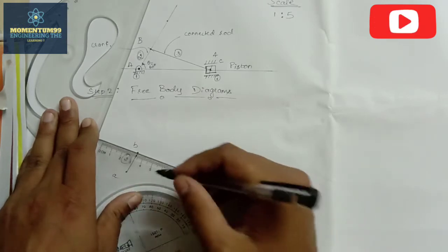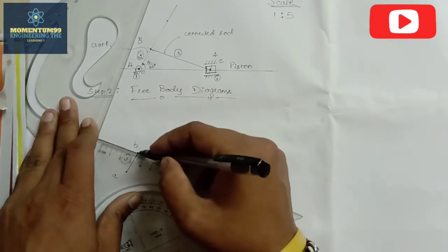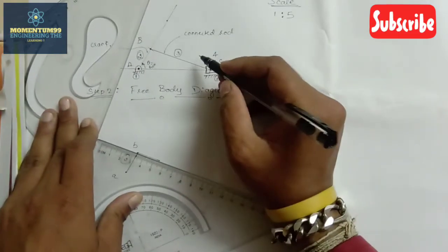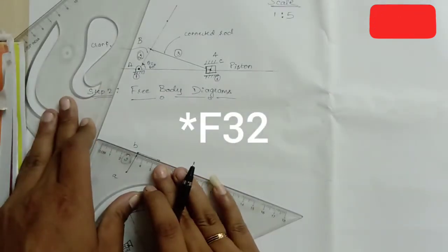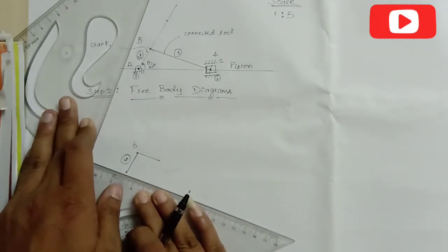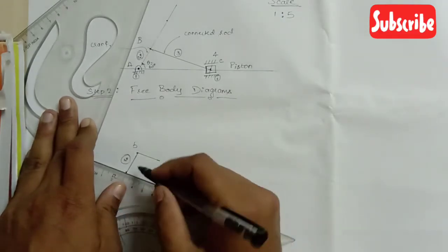Okay. Now after getting this, draw a line from the point B, so that you will get the direction of the force F23. Now again I also need another line of action, F12. F12 is parallel with respect to this. Just draw the line here to show this.